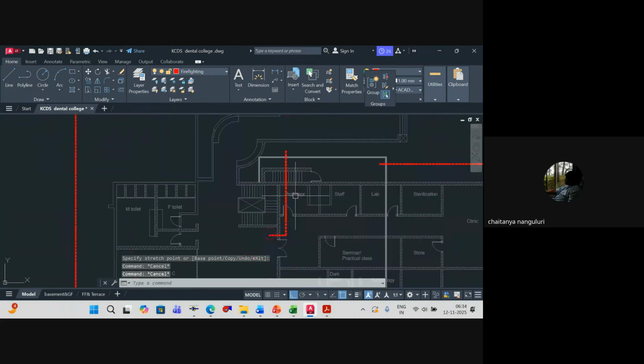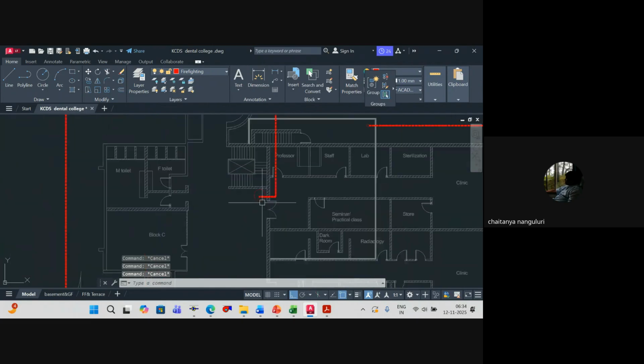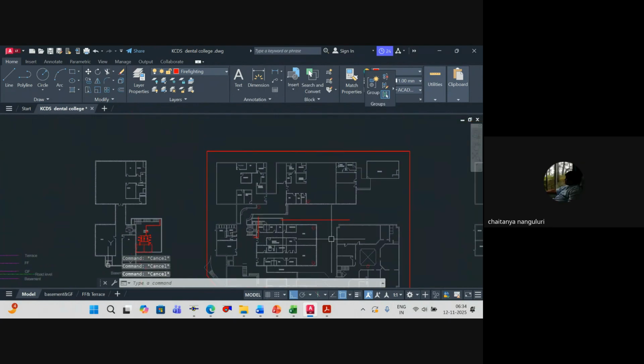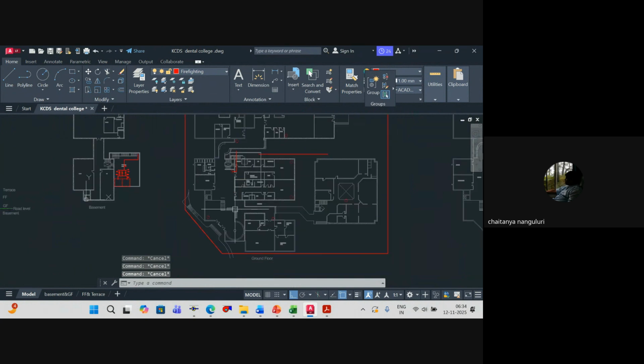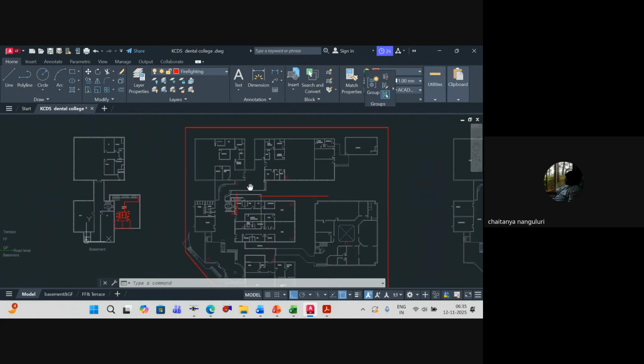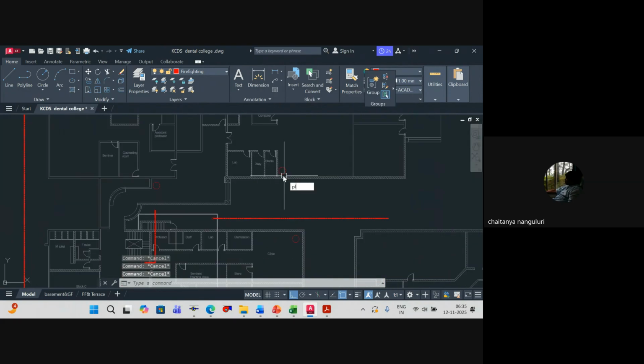Yes or no? Yes, from the external, I have to connect it to this one over here. Right. Let me assume this is one zone I've considered, and this probably is one more zone. Of course, we have to locate your hydrant location, that will decide anyway. So at this location, I wanted to have one more zone standpipe. So here we'll have it, here we'll have it.